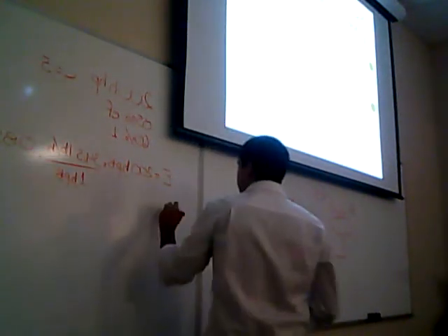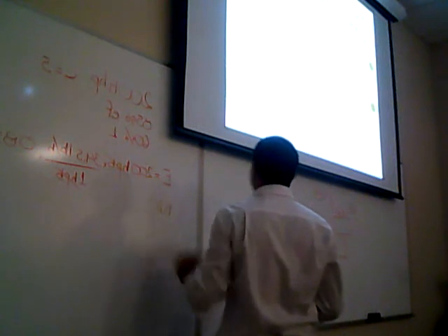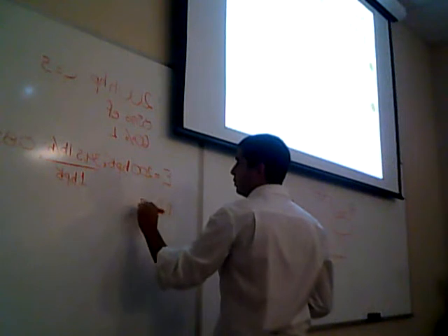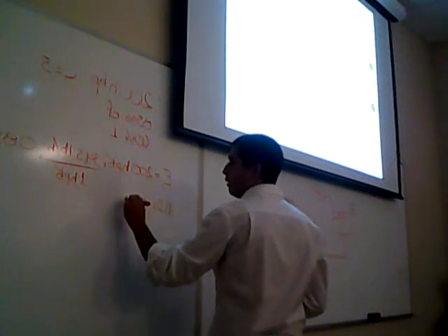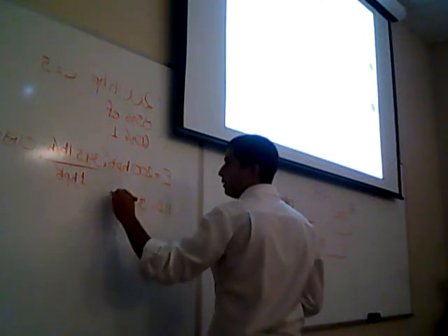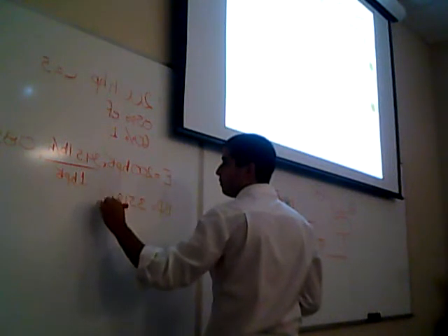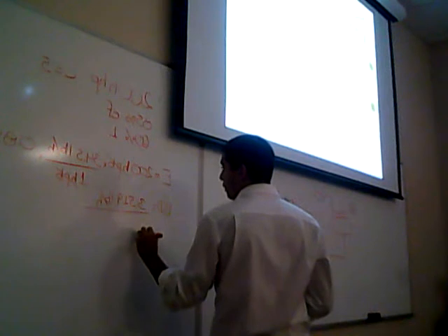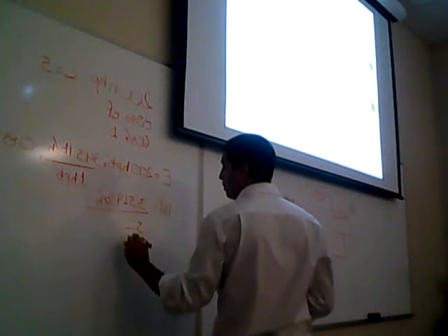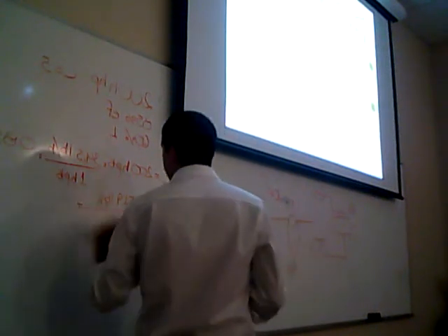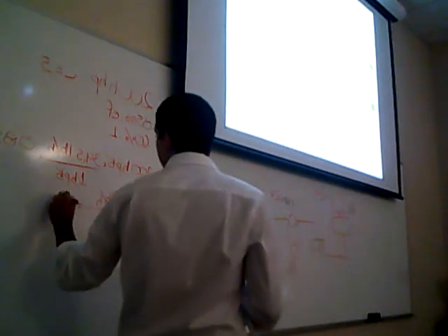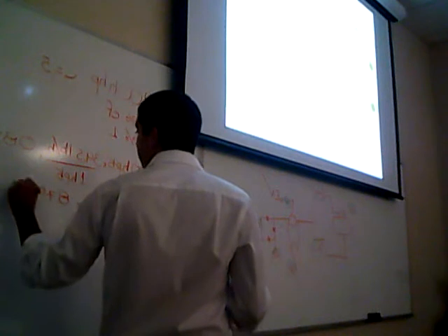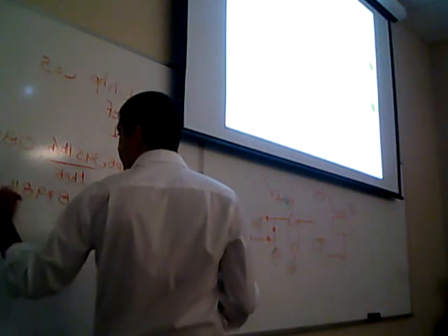The equation says that the blowdown is going to be E times 3,519 divided by the cycle of concentration 5 minus 1, and it's going to be 879.8 pounds per hour.